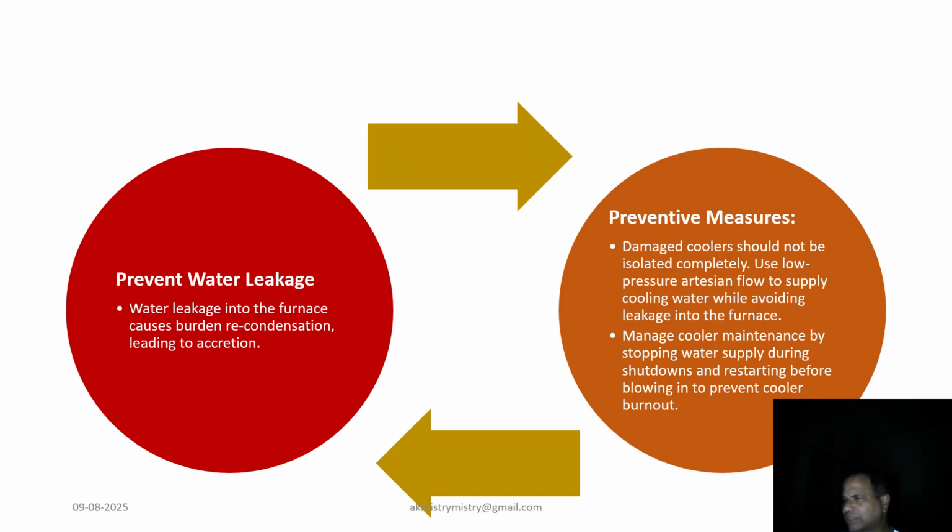So, in conclusion, preventing accretion requires a proactive and strategic approach. This strategy integrates three key areas: raw material optimization, operational adjustment, and regular monitoring. Historical lessons consistently highlight the importance of achieving a balance between raw material quality, gas flow, and operational discipline. By diligently addressing all these factors, a blast furnace can achieve enhanced reliability, longevity, and productivity.